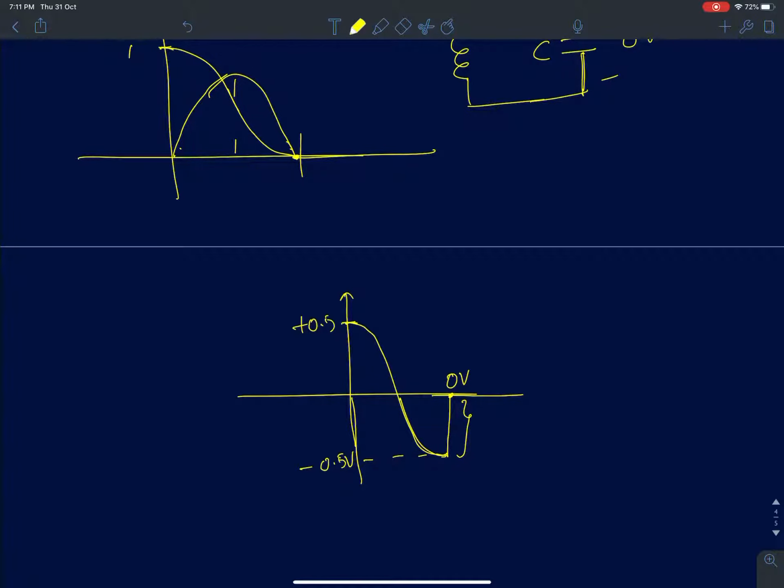So the only possible solution is, again, the voltage across the inductor cannot stay at minus 0.5, because otherwise it will start building current in it. That's not possible now. Okay, because for the inductor to build current, someone has to provide energy to it. On its own, when it starts from 0 current, it can't build a current. So the voltage across the inductor will also come to 0.